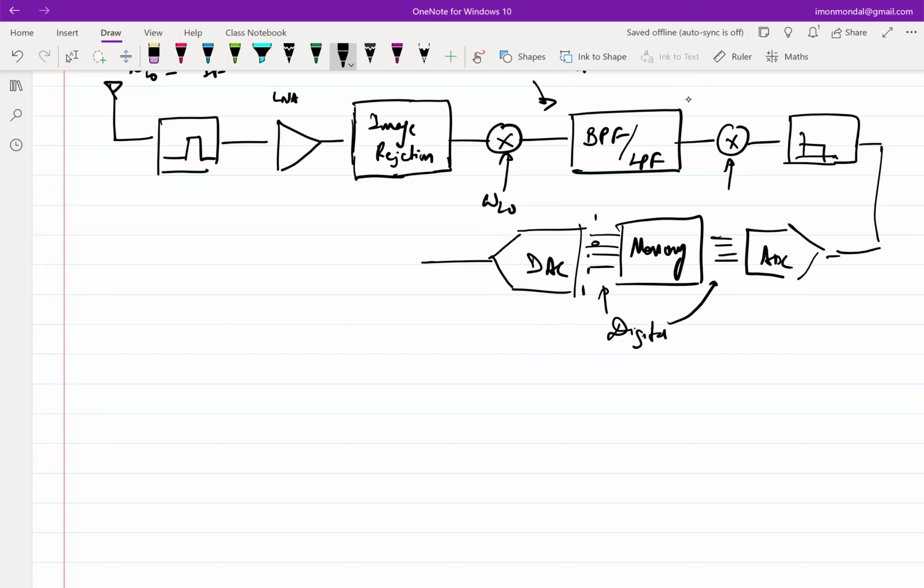Which means there are discrete levels, and which essentially means that the output of the DAC is not necessarily very smooth. You'll have a square wave, or depending on what type of DAC you have, you are going to have different types of waveforms scaled with respect to each other, which essentially is an analog form of the digital bits. Now, obviously, if you have scaled periodically sampled bits, you are going to have multiple harmonics or sidebands, just like you would have sidebands after you sample, right?